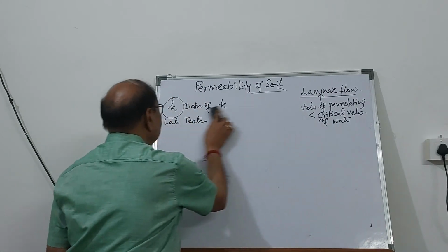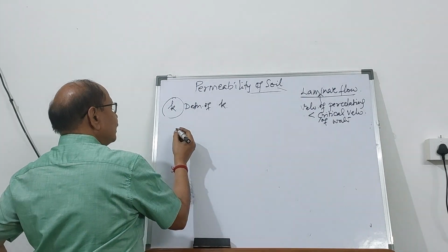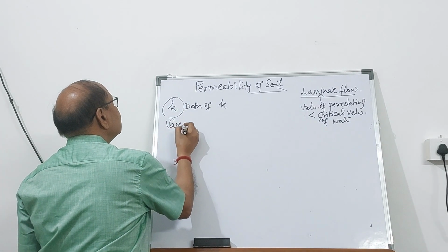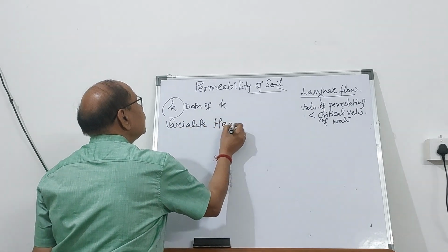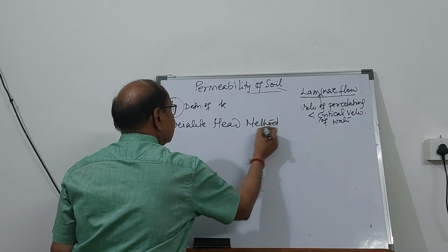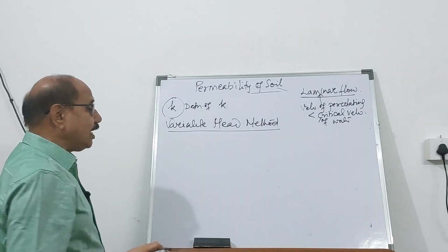Therefore, we go for another lab test, and that is called variable head method. This variable head method is normally used for fine grained soils.